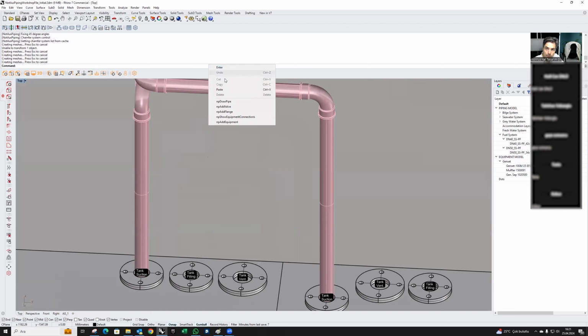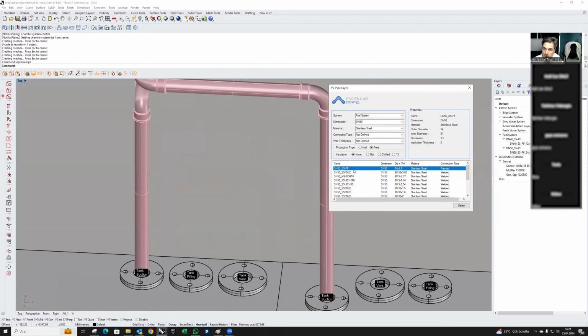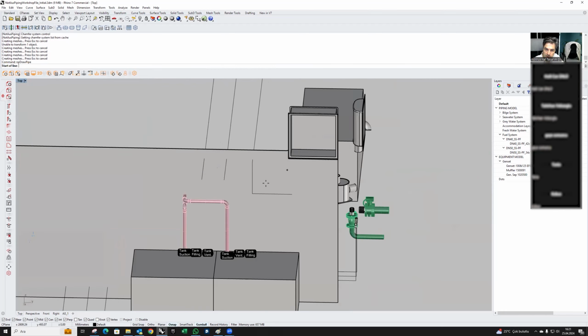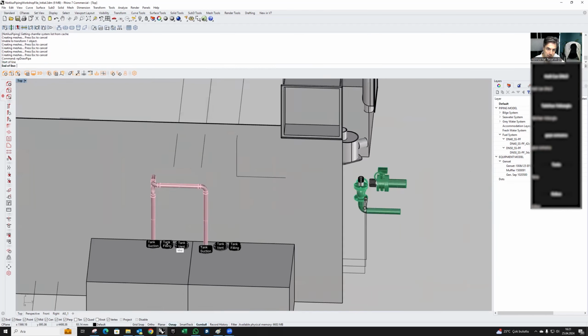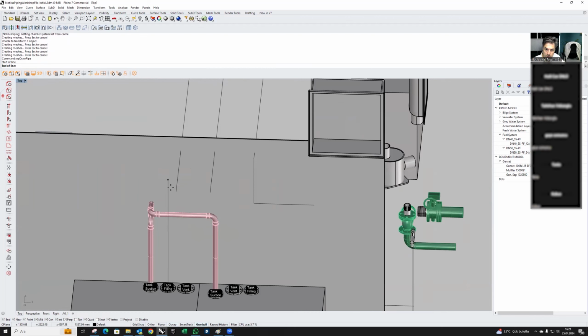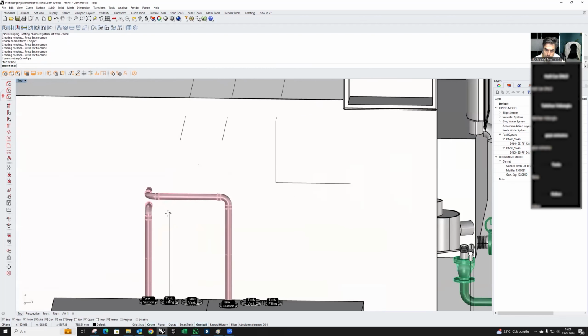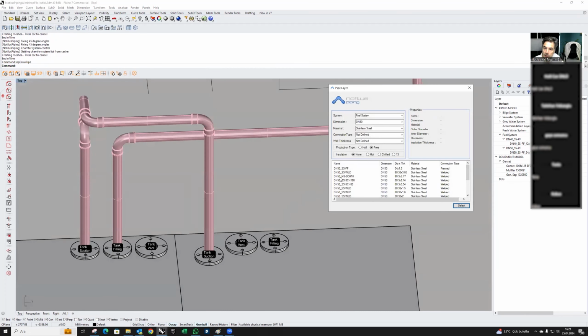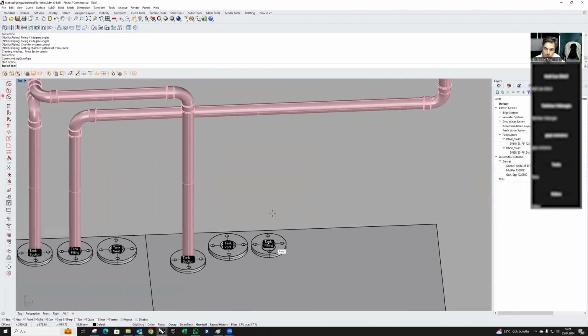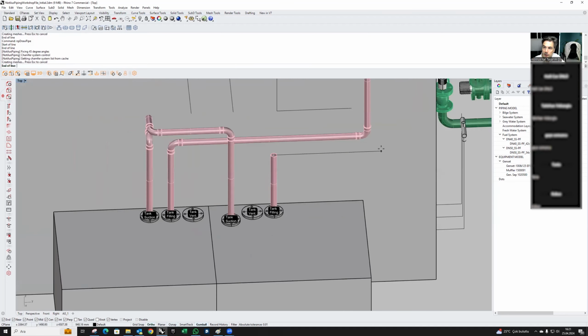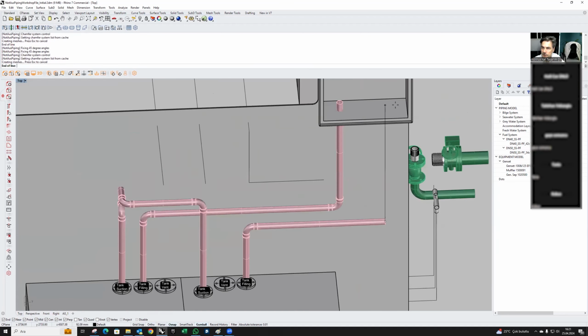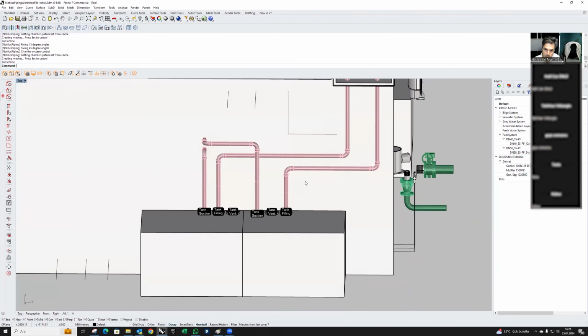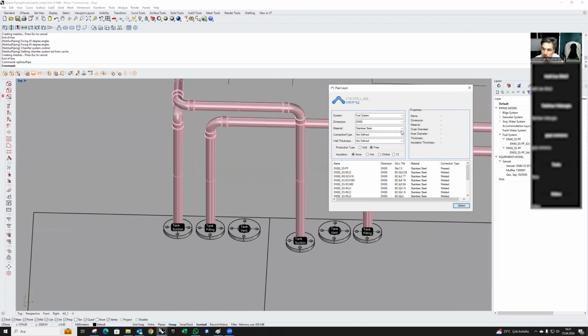We are here. So I will continue with the tank filling. Here is DN50. This is our filling station. So I will go to this line, up to this line, here and here. So I will make the second one, the tank filling line, here. I will go up here and give some distance to allow the air vent to go here. So air vents are DN65.